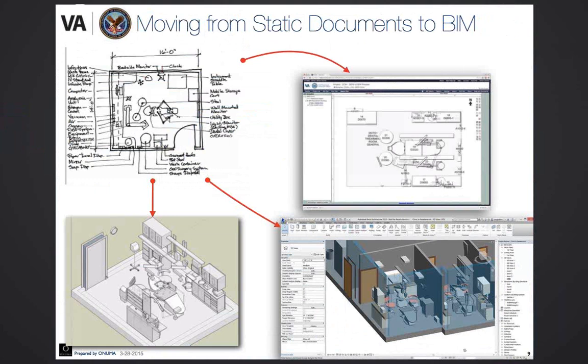So in concept, obviously that's a lot of very valuable data because it sets the stage of the requirements for a project, but we're saying by connecting SEPS, which is already a database, to BIM, Building Information Modeling, which is essentially a database connected to CAD or three-dimensional models, it automates the mundane work of getting the names of the space, equipment, the right equipment, and the right size of the equipment to the architectural teams as a starting point.